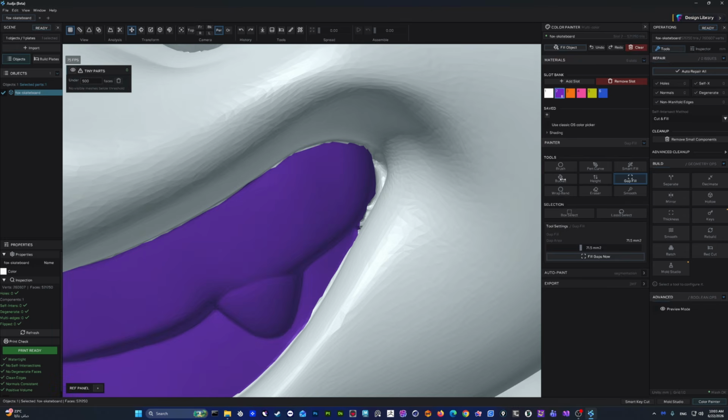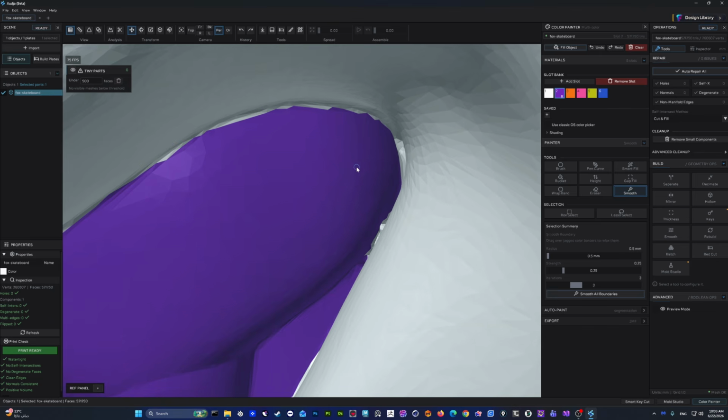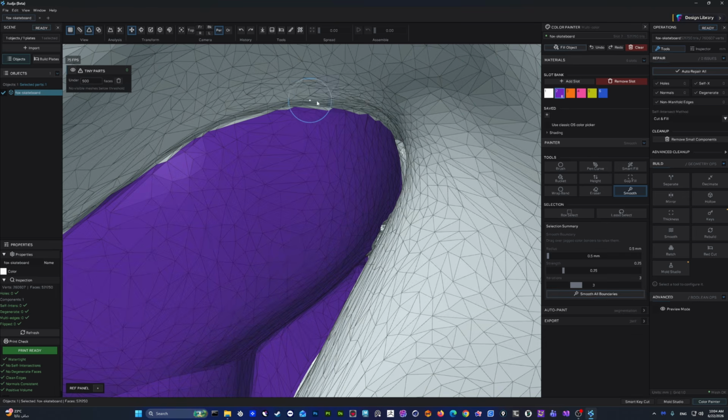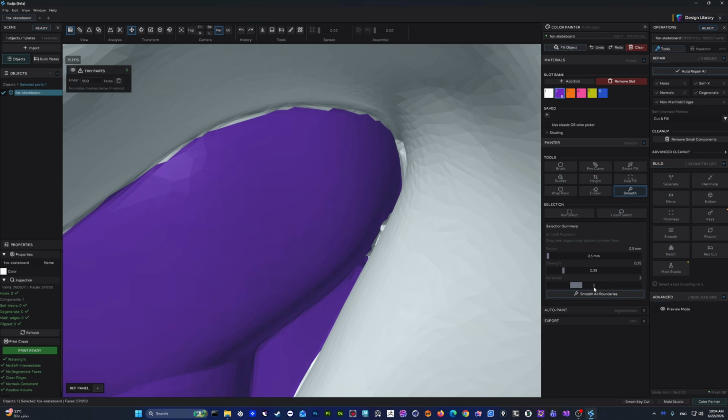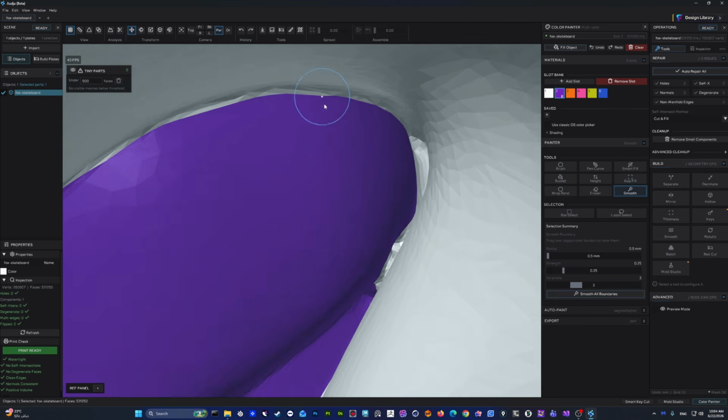All right. So I'm gonna go to smooth, and as I told you, I'm gonna press here, but actually don't smooth it too much, so it doesn't move the polygons of the mesh too much, and it's gonna destroy the mesh, creating self intersections and other issues here. So I prefer to press 2 or 3. That's actually the maximum for me. If I press once, and once maybe it's gonna be enough. So if I press on 3, and strength is 0.25 I guess, and press here. As you can see, it got smooth.